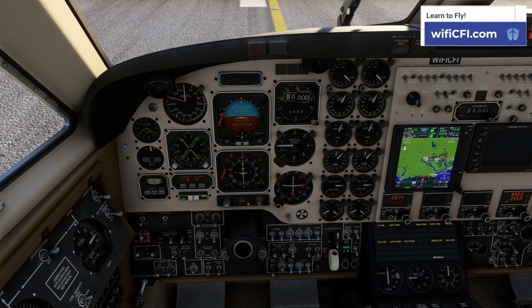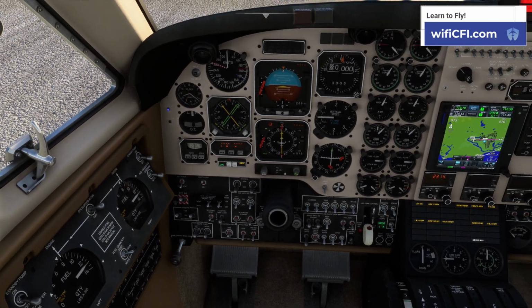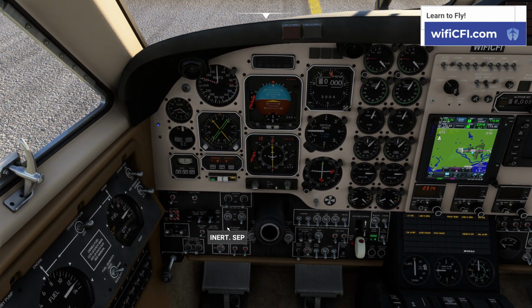Emergency exit secured and locked. Cabin door closed, secured and unlocked. Cabin door closed and locked. Seat belts adjusted and fastened. Parking brake is set. That's right down here. You can see it's pulled out, set. Fuel panel circuit breakers would come over here. Check, make sure these are all pressed in. They are. Engine ice fans, we'll go ahead and extend these for our engine start and taxi.